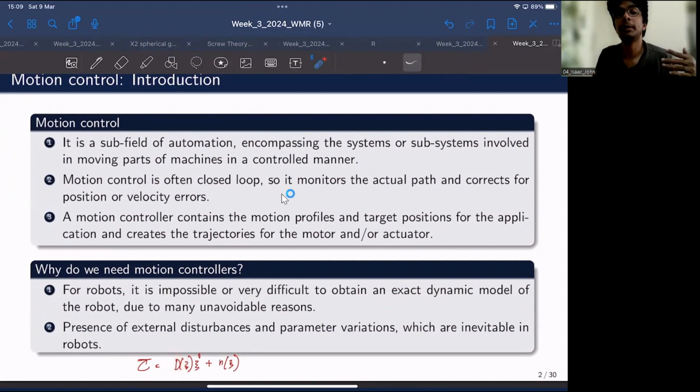And there could be things that you might not even have considered in the model. For example, this model does not account for friction in each of these joints. So friction is basically unmodeled, but if you assemble a system in real life, there will be some influence due to friction because there will be dissipative forces within the system, and here you don't have any dissipative forces.